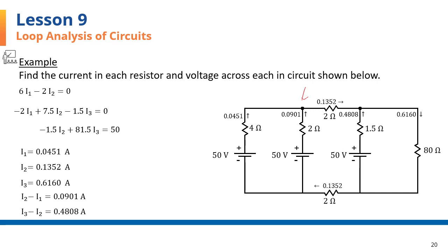You see that two currents are coming into the node and one current is leaving that node. So adding these two currents, we should get the value for this current, and you can see that checks out. Also for this node, there are two currents coming into it, and they should add up to the current that's leaving the node, and that also checks out.